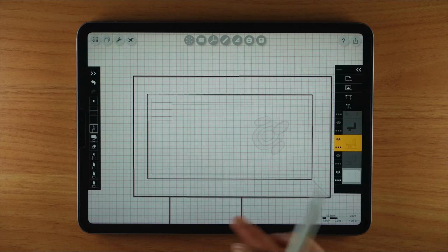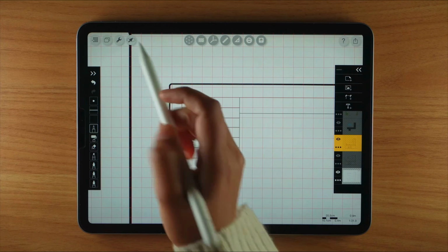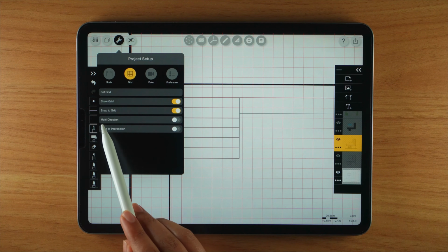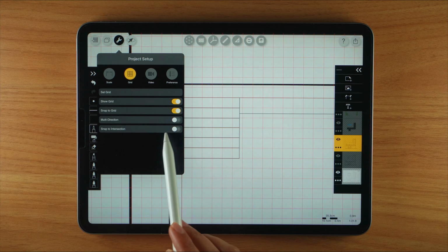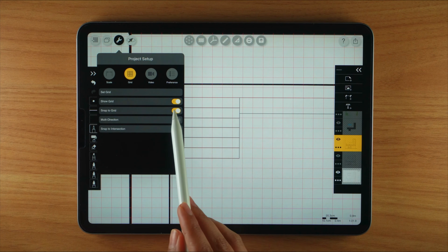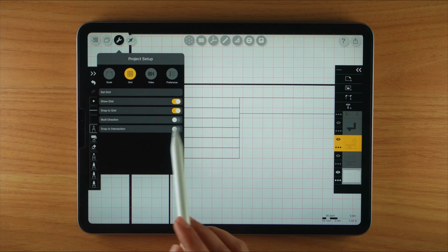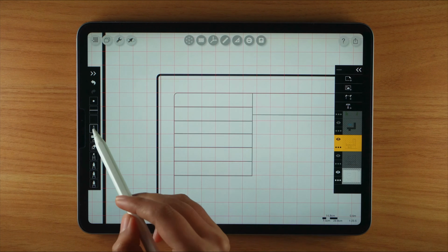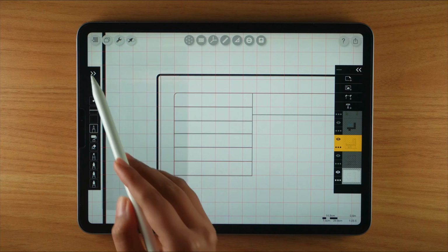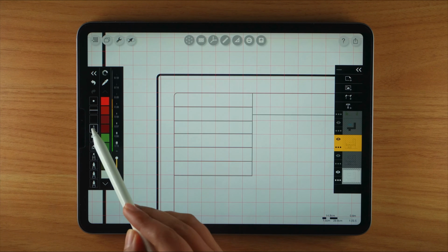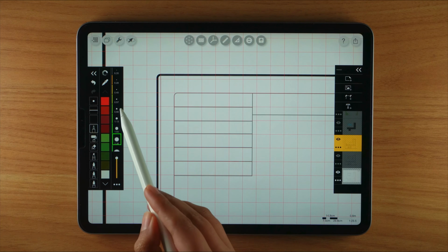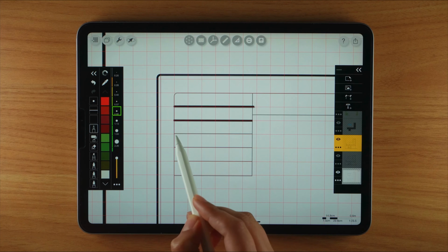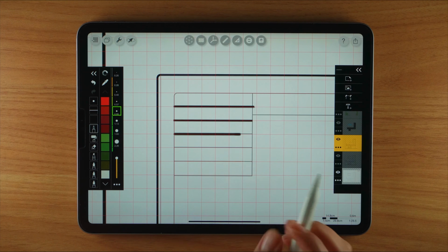In the settings, you can see the snap to grid is turned on. Now, every line I draw will snap to the grid, just like working in CAD. This is extremely helpful when creating walls, steps, or repetitive elements. For creating these pool steps, the Snap to Grid tool makes the process very fast. I don't need to create offsets one by one. I have already set my grid and spacing. So now I can quickly draft the steps. I am simply creating the lines like this.